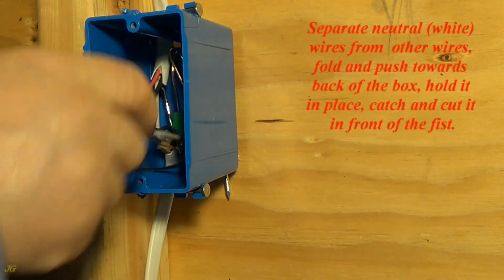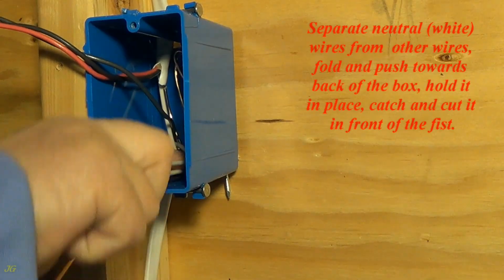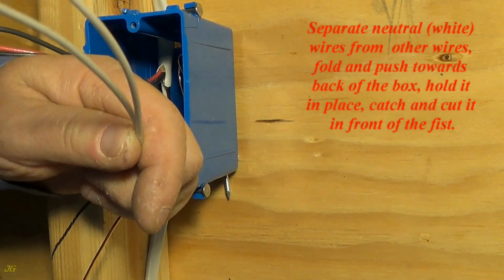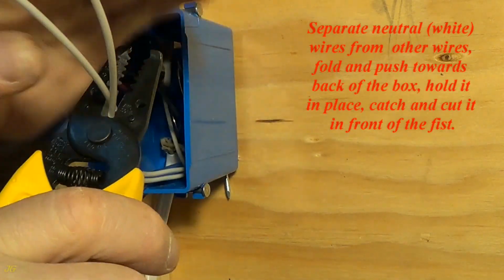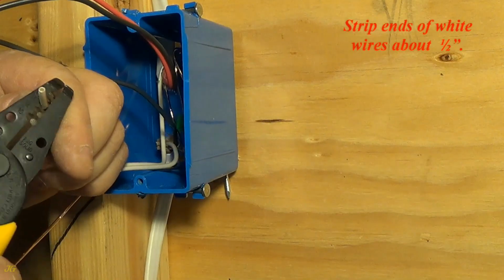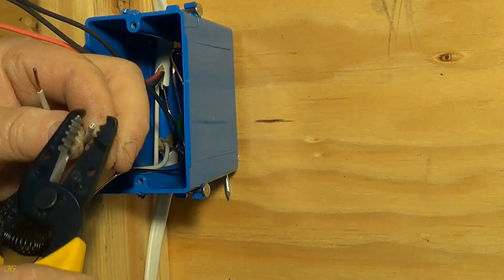Separate neutral, white wires from other wires. Fold and push towards back of the box, hold it in place, catch and cut it in front of the fist. Strip ends of white wires about 1/2 inch.